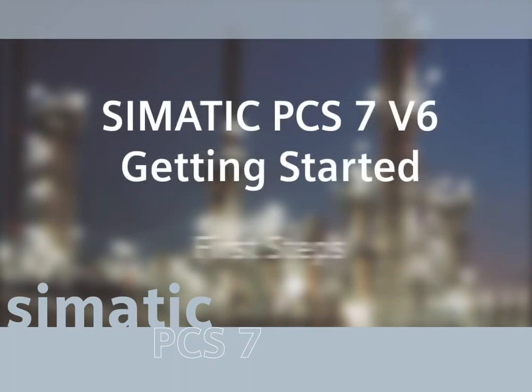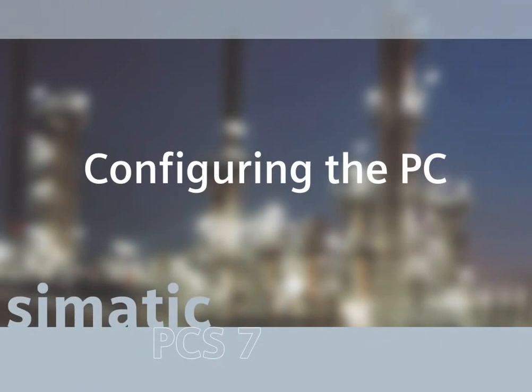This video is designed to follow the manual Getting Started PCS7 First Steps, but also demonstrates some additional work steps beyond what is included in the document. In this sequence, we are going to show you how to configure your computer before you actually start configuring the SIMATIC PCS7 application. This step has to be carried out once at the beginning of the configuration phase. It is basically required to define the communication links between the automation components and to create the project itself.